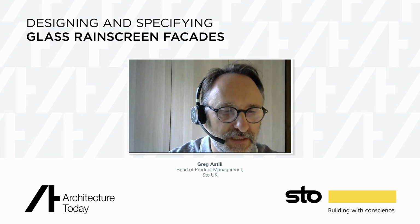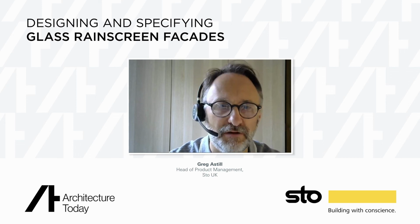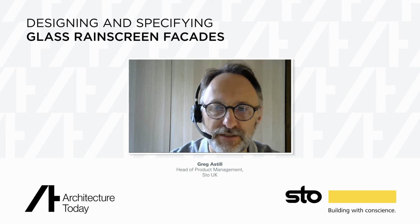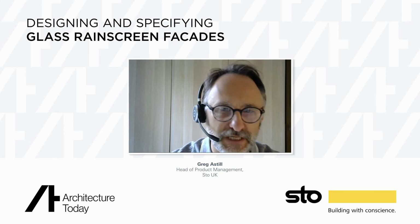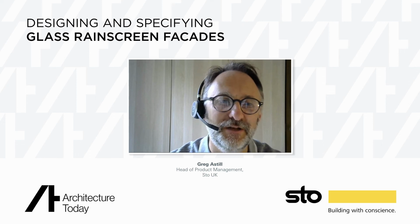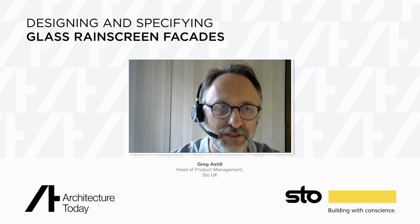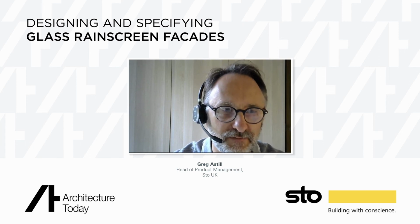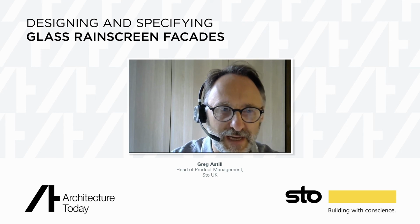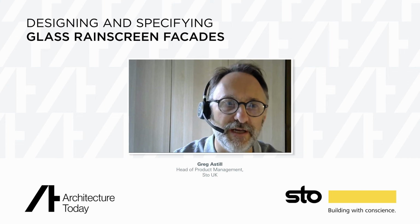You've basically got hard impact, which simulates a stone or a sharp object being thrown or projected into the glass. And you have a soft impact, which is potentially someone stumbling or falling into the glass, or, on a high building, something like a cradle being used for cleaning, which then swings and impacts into the glass. These have a variety of levels of impact, from relatively minor to actually pretty high.